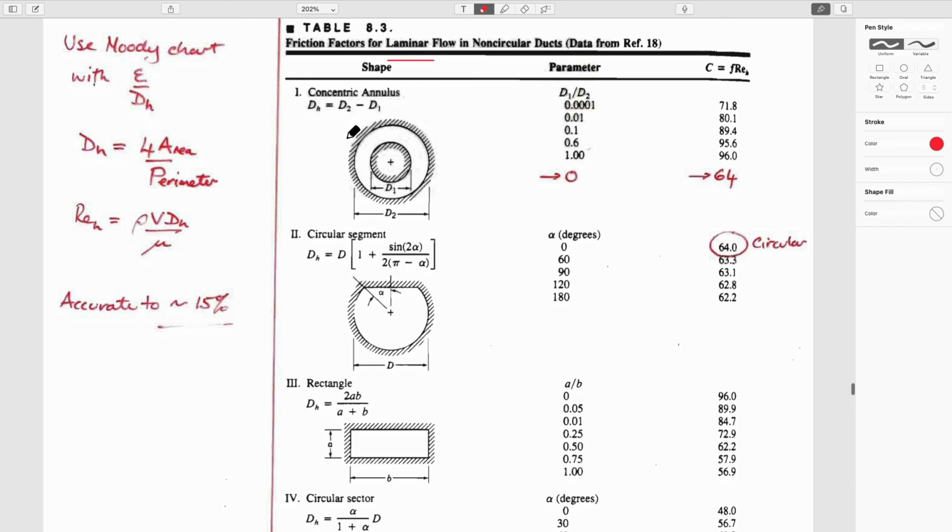And so the appropriate magnitudes for those would be things that would make sense. If you have a circular section that has a central core in it, then flow is only within this annulus. Then you can get the magnitudes of these friction factors. It was 64 over Reynolds number before, for a circular section. But now this C is equal to something different.